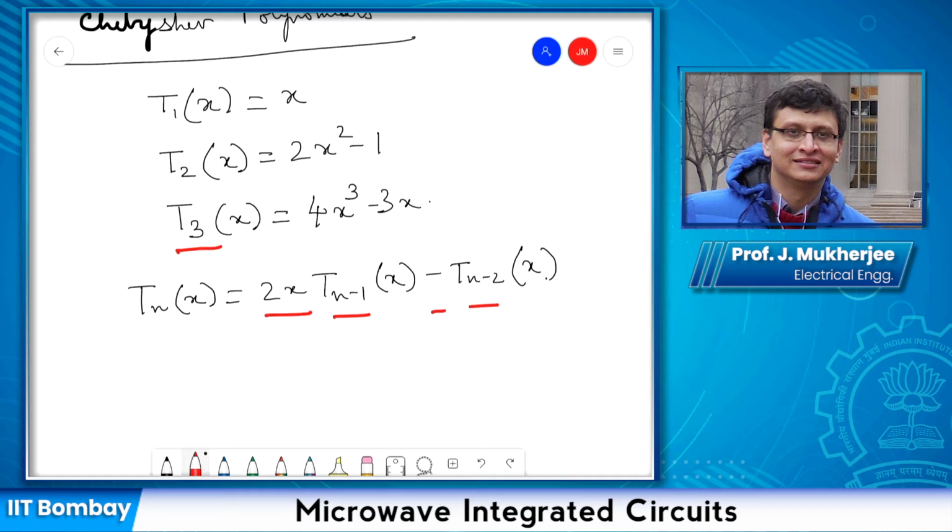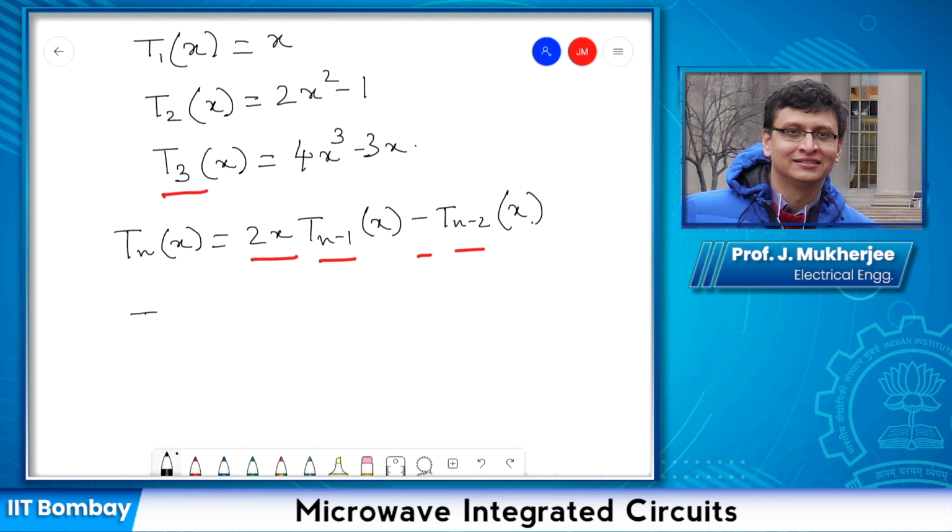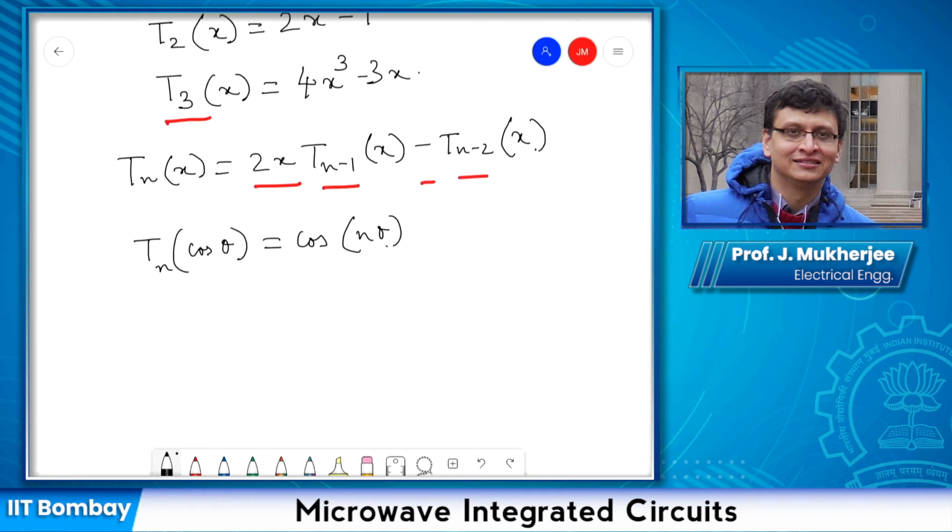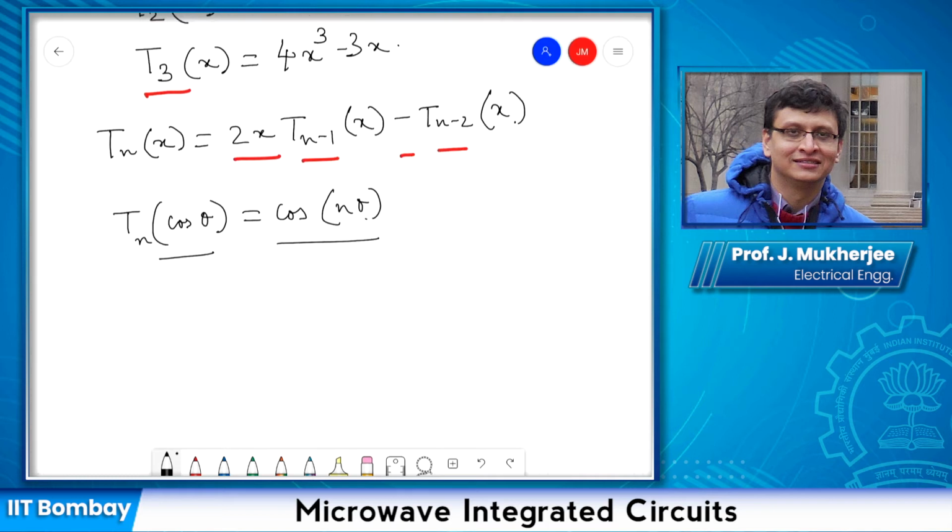Okay. Now a consequence of this polynomial is we can rewrite the nth order Chebyshev polynomial like this. So what this means is that if this argument is between -1 and +1, then the Chebyshev polynomial itself will be between -1 and +1. In other words, another way to write it is saying that if modulus of x is less than 1, then the modulus of the nth order Chebyshev polynomial will also be less than 1. Now, this was about the Chebyshev polynomials, but suppose we plot the Chebyshev polynomials versus x, how will they look?